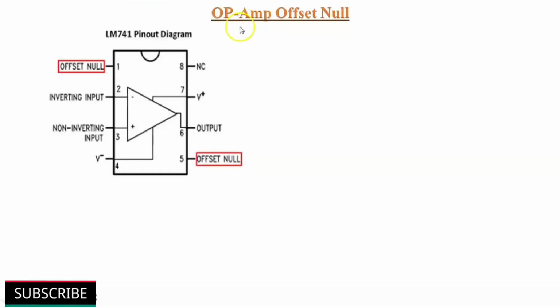The other method to reduce input offset voltage is by using offset null circuits. There are usually provisions made by the manufacturer to trim the offset voltage. Usually 2 extra terminals on the op-amp package are reserved for offset null pins. On a single op-amp such as LM741 and 3130, the offset null connection points are pin number 1 and 5 on the 8-pin chip package.